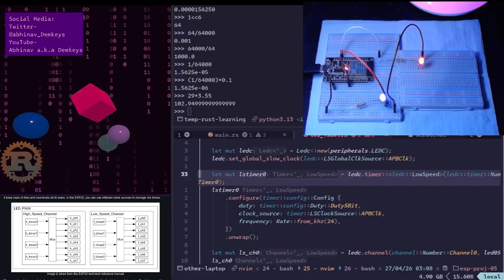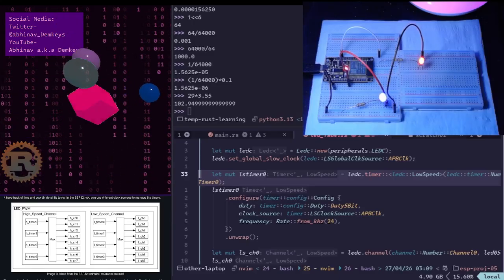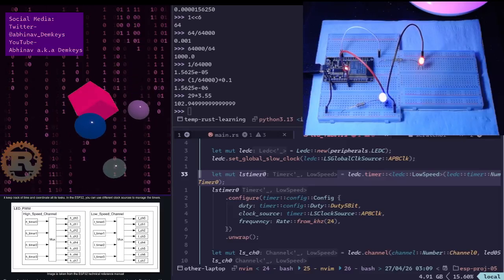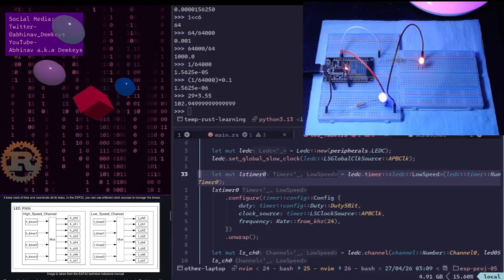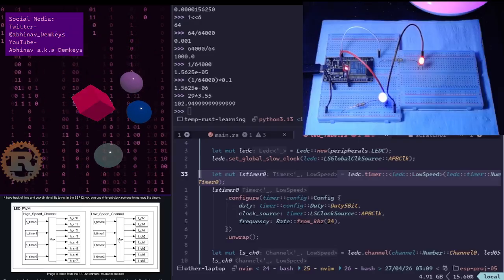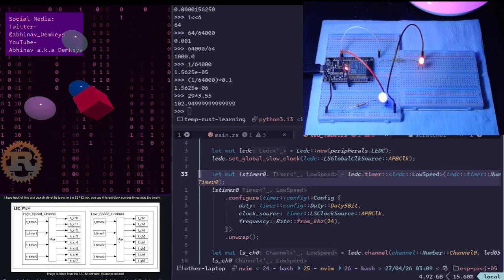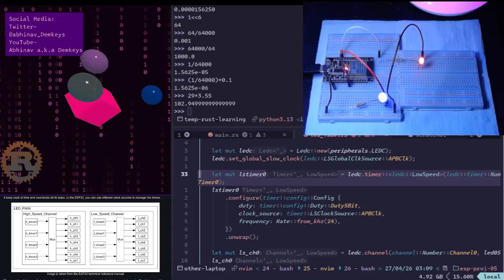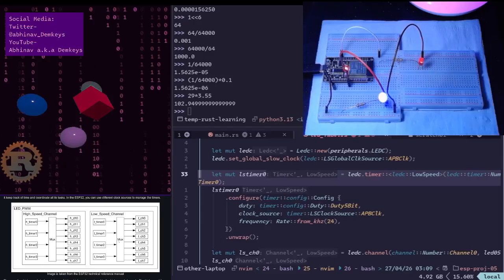This is a great example of how no STD Rust crates like ESP-HAL balance hardware reality with API consistency. Here is the breakdown of why you're seeing redundant settings and one option enums. The one option enum mystery. The reason LS Global Clock Source currently only shows APB clock for you is likely a combination of two things.